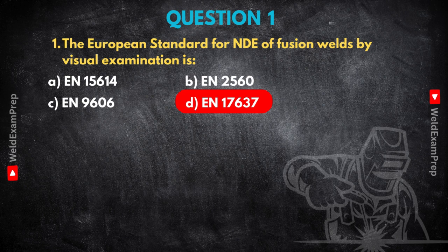Okay. And finally, EN 9606. This is about welder qualification testing. It sets out the requirements for qualifying the welders themselves for fusion welding of steels. It ensures the person doing the welding, the chef, precisely, the chef in our analogy, has the necessary skills and competency to follow that qualified welding procedure. So it's about the individual's ability, not the visual inspection process. That's a really fantastic breakdown.